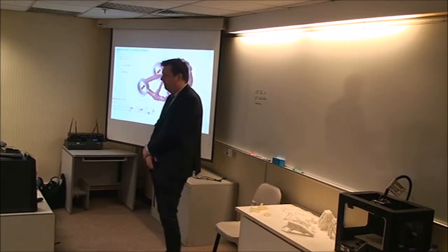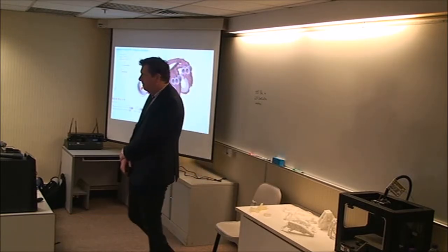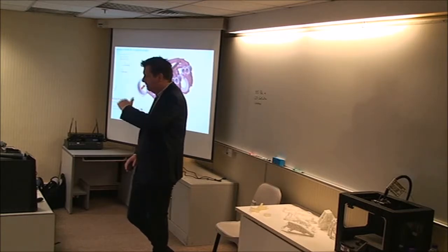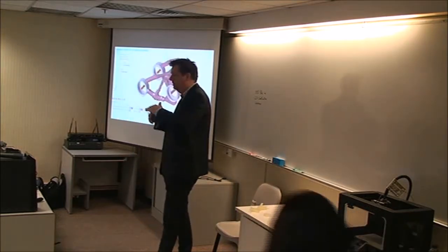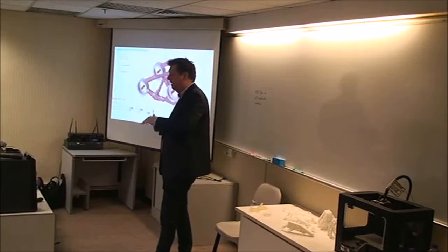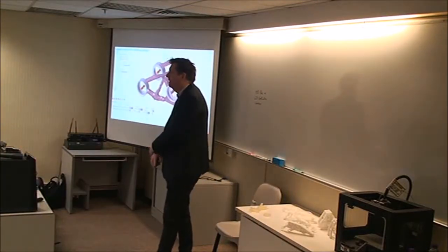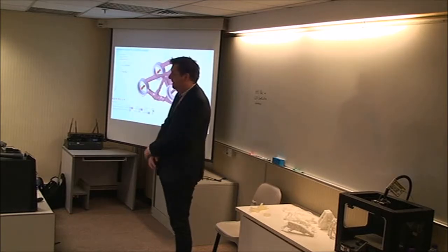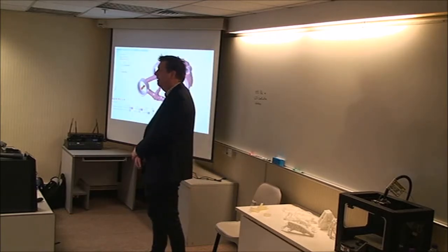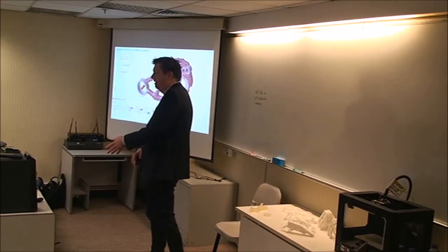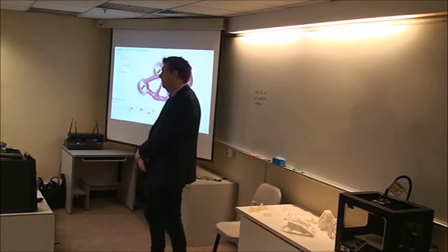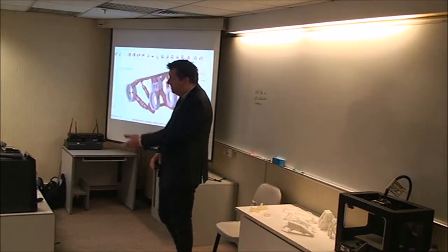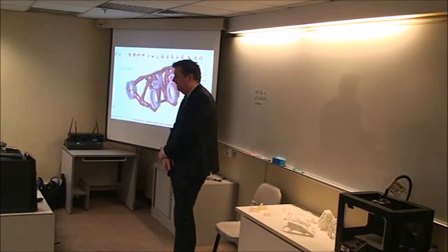And then you can compare your multiple concepts. So down the bottom there, you can run many of these iterations. We've got these tools. You can compare the mass and displacement just in this little table across the bottom. So really quickly you can drill into what are the best design options. One of them might perform better, but you think it looks terrible, so you go for the one that looks better maybe. And then this is the one-click reanalysis. You've got your result, and it really is this simple.